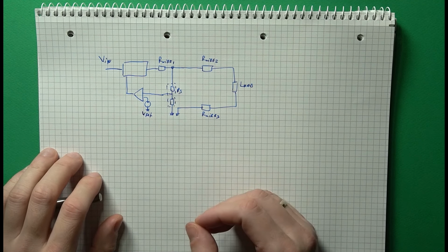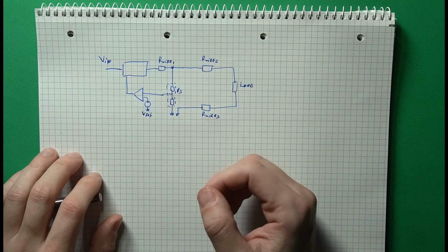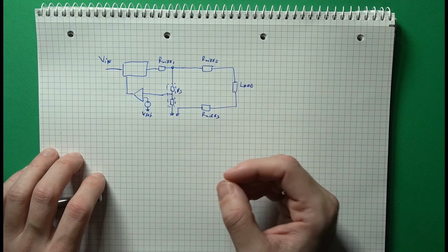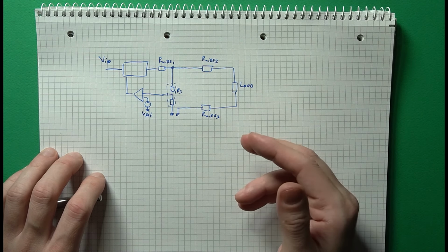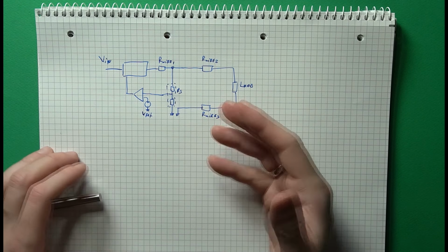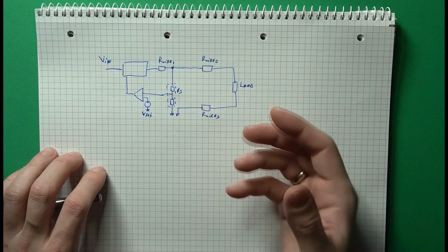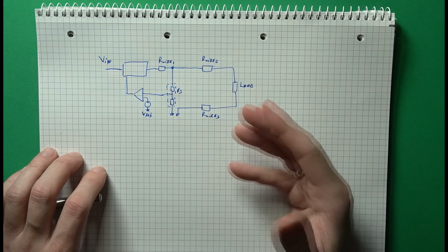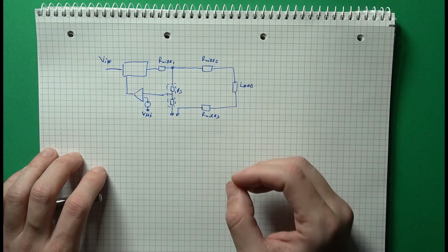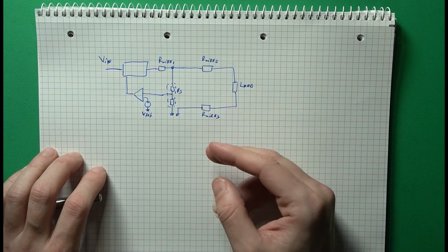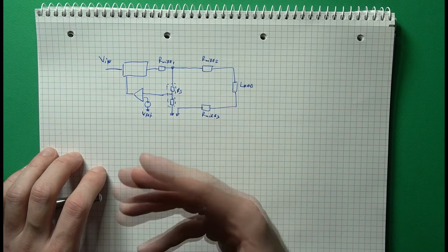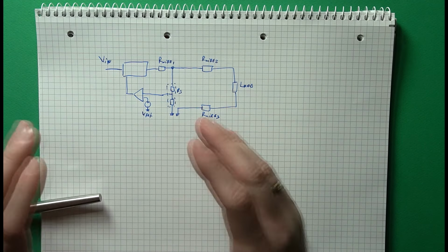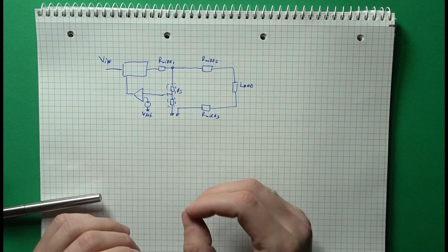Here there are two big things to consider: the resistor divider itself and the exact measurement point. So part of the output voltage tolerance will be impacted by the resistor tolerances. Using 0.1% resistors will make a far more precise power supply than using 5% resistors, but at the same time, there's no point in investing in extreme precision resistors if the internal reference has a high tolerance. In the end, you need to consider the global tolerance of all of the supply elements combined.